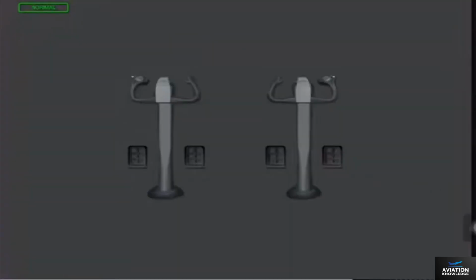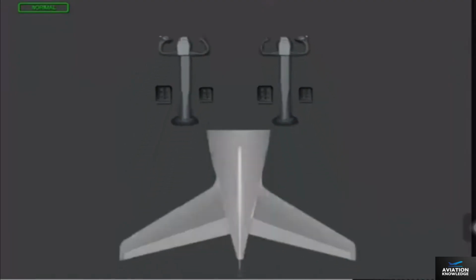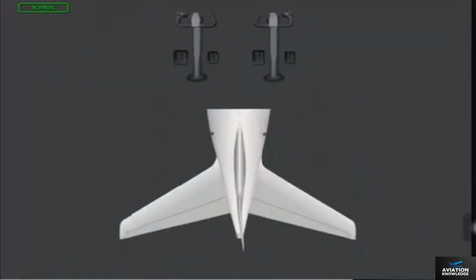In normal mode, airplane yaw control characteristics are similar to conventional airplanes. Unlike conventional airplanes, the rudder pedals do not directly position the rudder surface in flight. Instead, the pedals command a side-slip maneuver, with the airplane's side-slip angle dependent on pedal displacement. The flight control system will then position the rudder to generate the commanded maneuver. The system constantly monitors airplane response to pilot inputs and repositions the rudder as necessary.